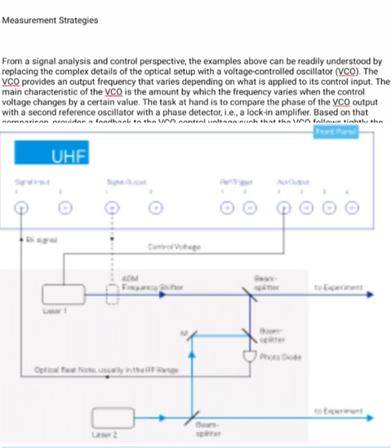PID error. The LabOne toolset, consisting of scope, spectrum analyzer, sweeper and plotter, enables an integrated analysis and monitoring of the locking quality. For instance, you can visualize the PID error as a histogram to spot deviations from a Gaussian, which indicate that something in your setup does not work as expected. The frequency range of the UHF-LI 600 MHz allows you to sweep the frequency difference between the reference and the locked lasers over a large range.